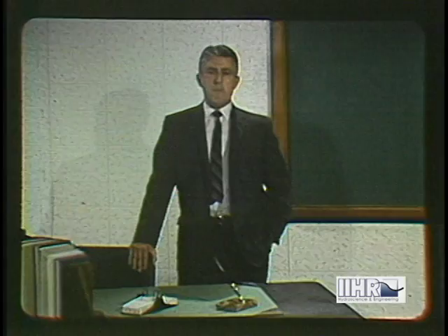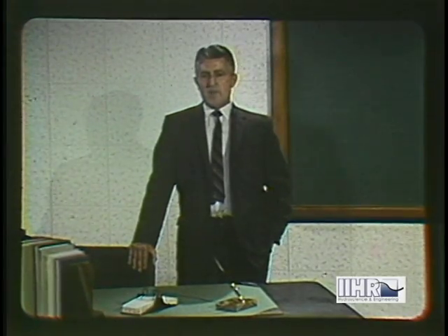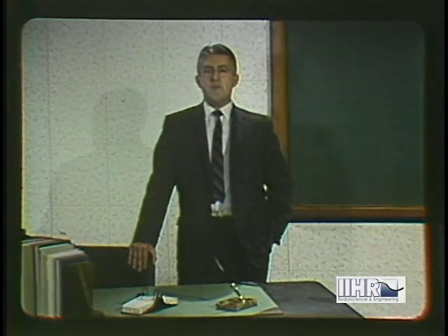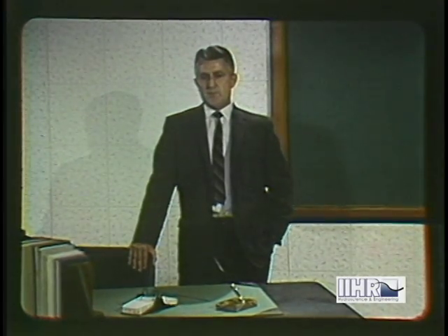The difference between these two contrasting patterns of motion is that the first was steady or invariable with time, and the second was unsteady or variable with time. For a constant relative velocity between foil and fluid, the one pattern can be changed into the other by the principle of relative motion. In other words, the difference is a matter of viewpoint, regardless of whether the fluid is stationary and the model moving, as in a towing tank, or the model is stationary and the fluid moving, as in a wind tunnel or water tunnel. In either case, the unsteadiness is the result of relative motion between the model and the point of observation.